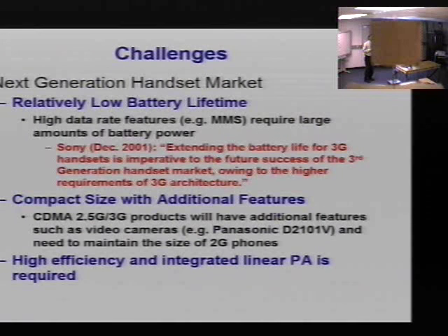Well, okay, you have to think about it more on a frame basis, even in the CDMA realm. A frame on CDMA 2000 is 20 milliseconds. I have to meet average ACPR over the frame, a lot of people tell me.